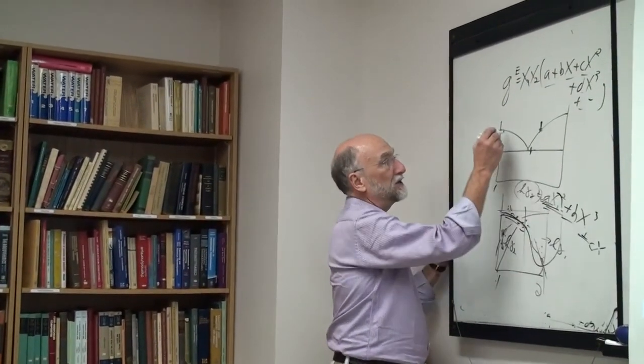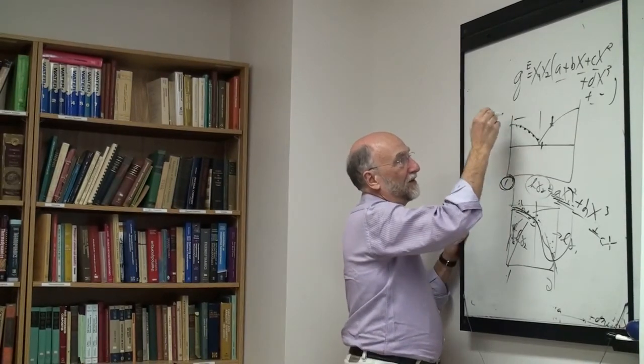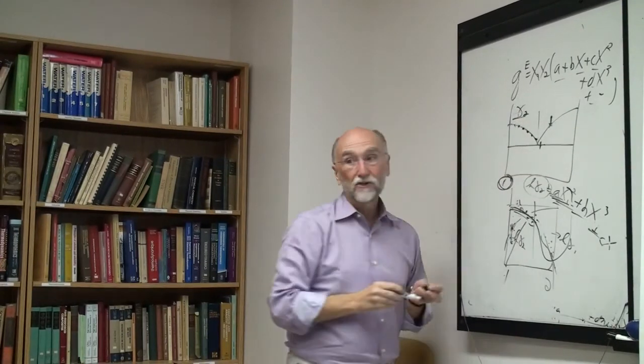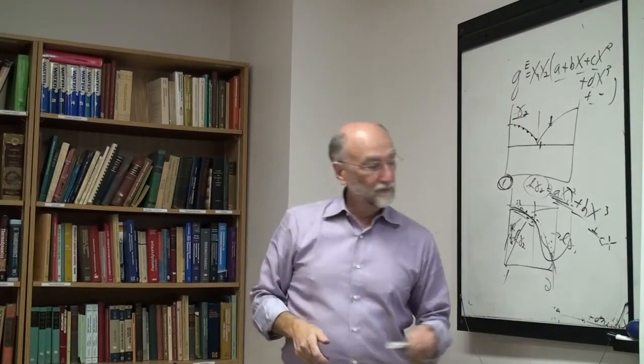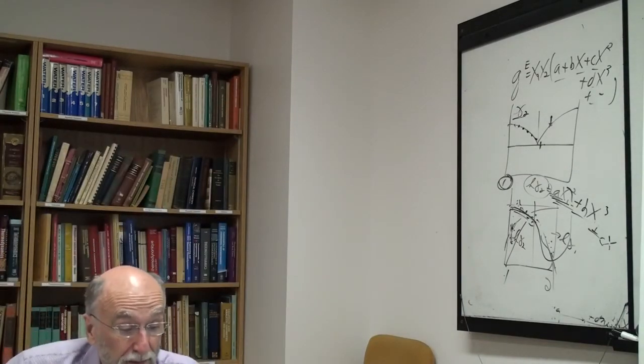And the final thing is, just because you look at an optimization and it looks beautiful, every single datum has been fitted, that doesn't mean that all the other properties are going to be good or correct. They might be or they might not be. You've got to think about it. The most flagrant thing is that you have a very nice fit to the liquidus over here of component 1, and then you assume that this means that gamma 2 in this region is good, and it can be really, really bad, unless other additional measurements are available.